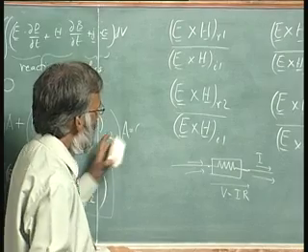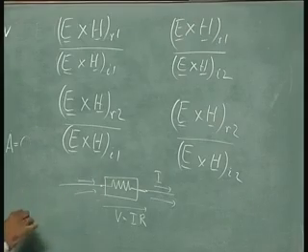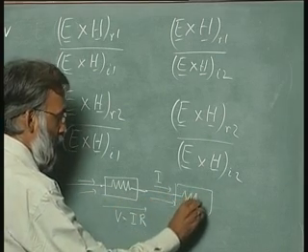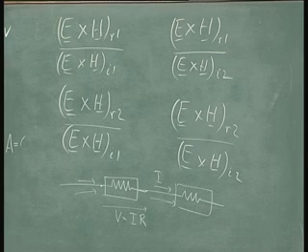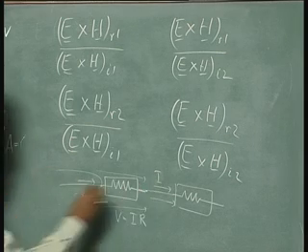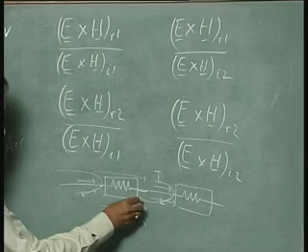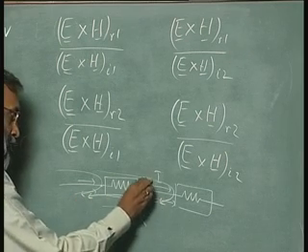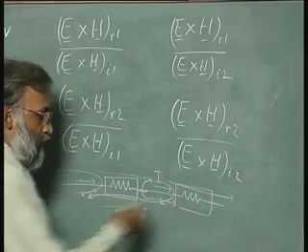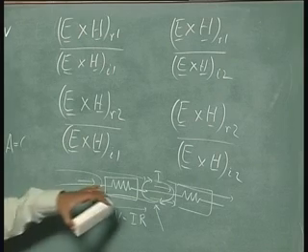But here the power actually flows in more complicated ways. Some of the power from the battery is actually reflecting, and if you had another resistor in a high frequency network, what will happen is some of the power will reflect, some of it will transmit, some will reflect off the second resistor, come back, some of it will transmit, some will reflect again, some of this energy transmits, and so on and so forth. So, you can see you will have some very complicated things happening here between elements,